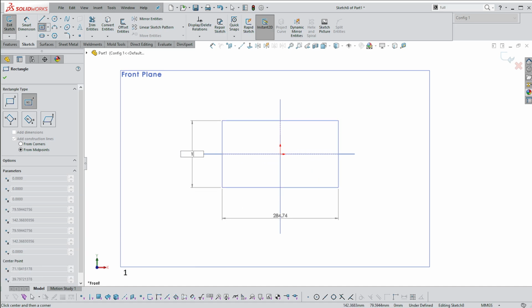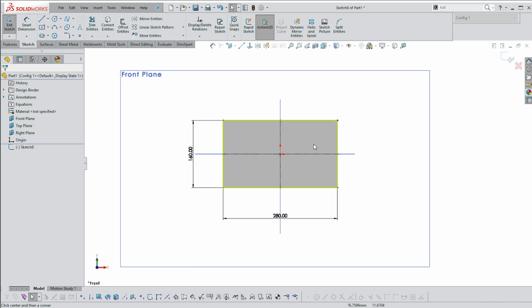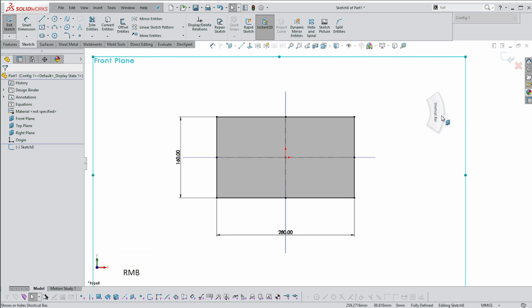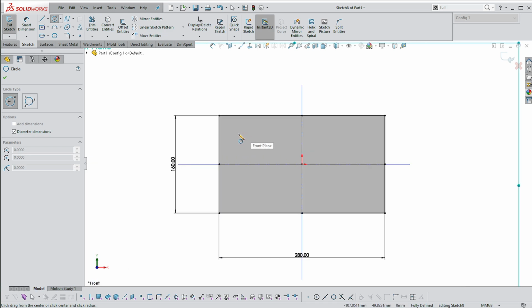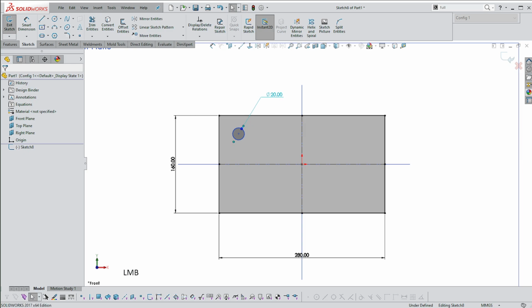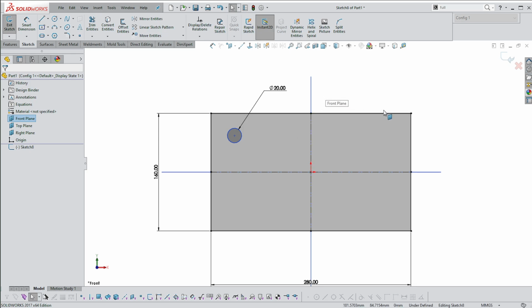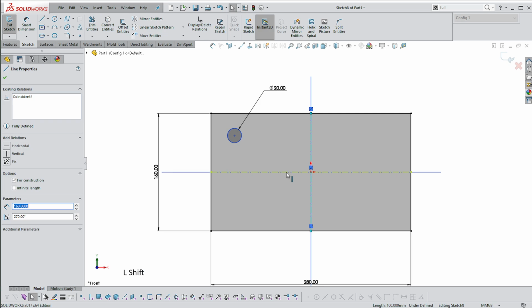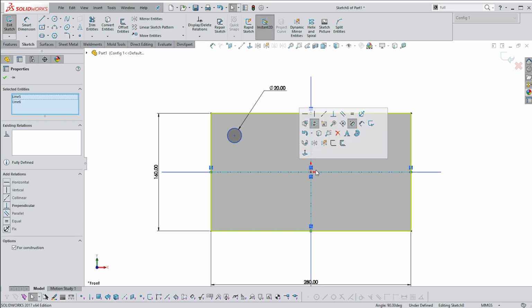So I'm just going to round this item off. Let's assume this were some sort of piece of wood that you wanted to put some holes into, and that you modeled this up in your Solidworks program, and you now wanted to tell either yourself or someone else that you want a hole of 20 millimeters and where do you want to put it. So at the moment, because I've chosen to put this block of wood centrally, it has center lines. We would assume that you would draw center lines on your block of wood, and we're going to use the center lines as our datums corresponding with the y and the x-axis.